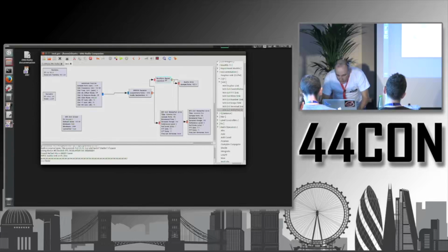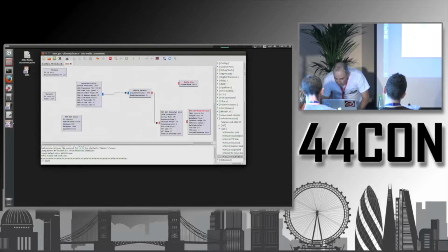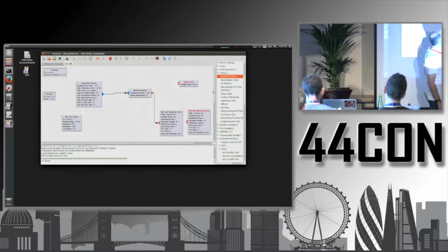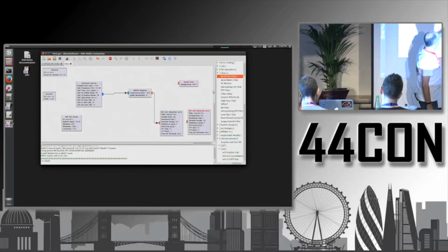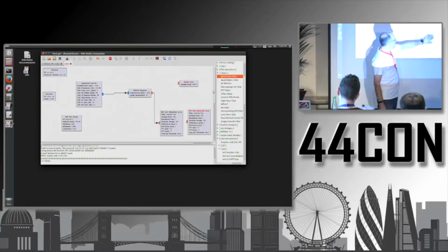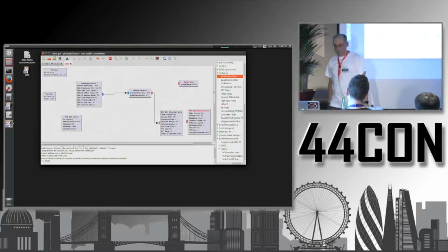So I'm removing the multiplier. And I'm going to filters. And here, bandpass filter, this one here. You can drag this one here and put it between the demodulator and the audio sink, and then you connect the waterfall sink to the demodulator and the second one to the output of the filter.